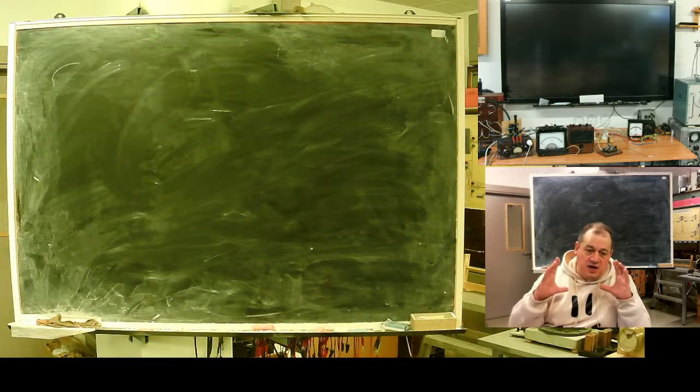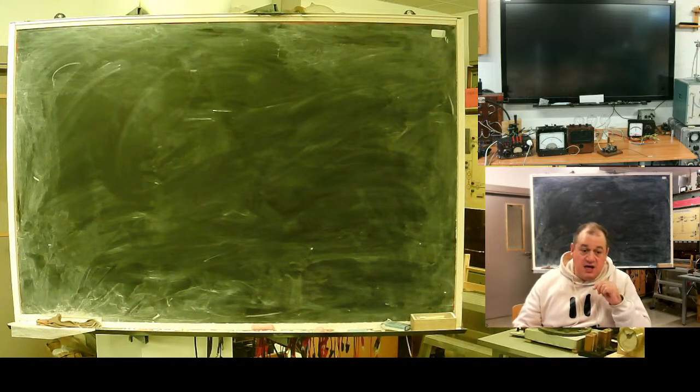For modern machines, we can expect aluminium castings and aluminium shroud around the main stator magnetic system, which is made of steel shields and put in a shroud. Old machines had cast iron shrouds, again with good magnetic conductivity.